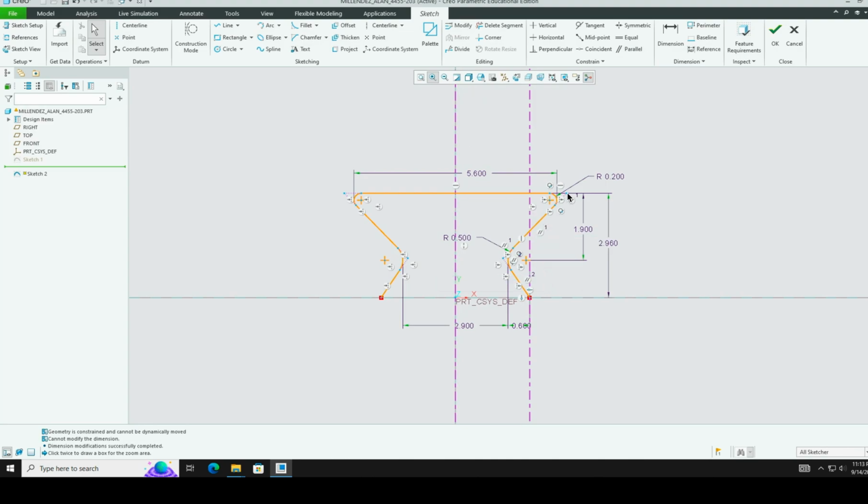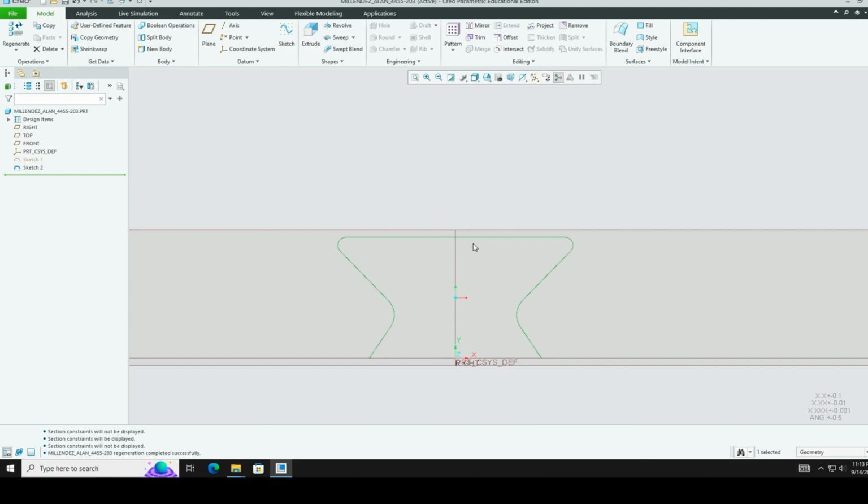Now sometimes you see all these markings about constraints. If you want to remove those constraints, I believe you can just do a filter here. SketchUp display filter. You click that, you can remove the constraints display, and that will clean up the drawing, right? But just to see them better, the dimensions are correct and everything. And once you have them correct, you can always bring them back here. Okay, this one here, constraint display. Sometimes you need that, sometimes you don't. Okay, so we're done. We click OK.